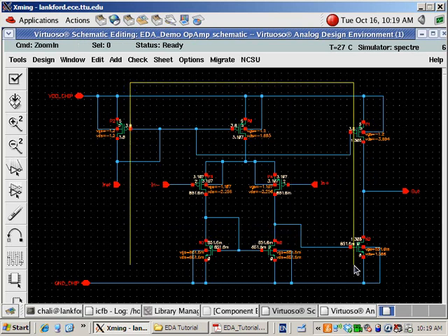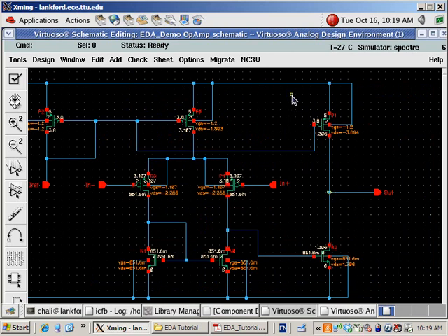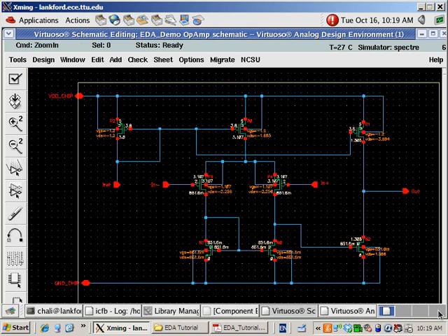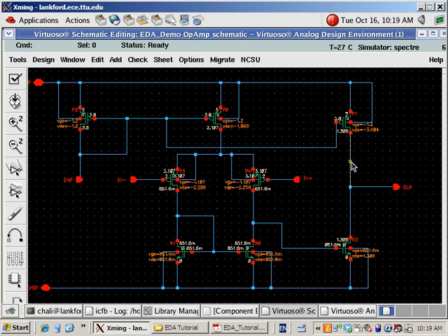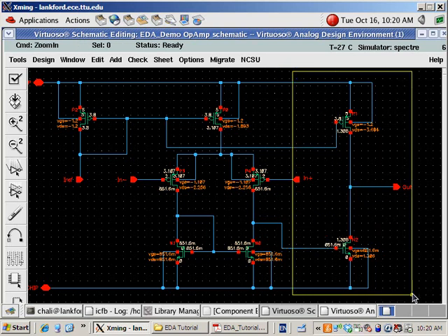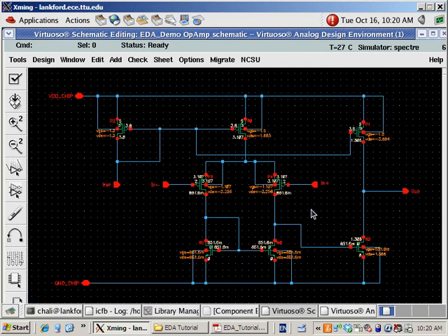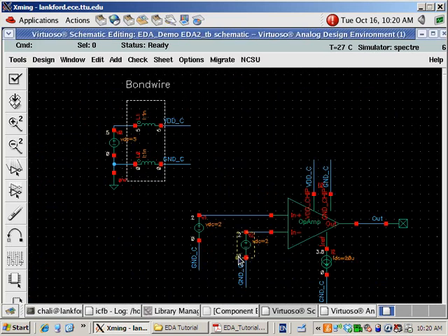So one problem we have already seen, the output voltage is not very nice. The output voltage is 1.3 volt. It's closer to the ground and further away from the VDD. VDD is 5 volt, right? And actually it's difficult for us to tune this voltage right now because we have a very high gain from here to here, right? And this is one example to demonstrate that an open loop amplifier doesn't work very well. So our next thing is to add a feedback loop.